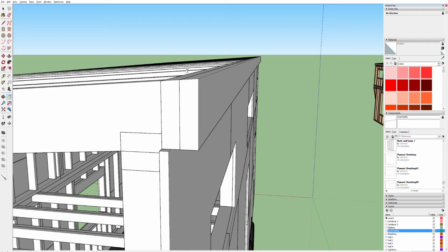And then we're going to have some drip edge, which is basically a piece of steel flashing or any kind of metal flashing that is nailed down to the sheathing and these blocks most likely with an approximately 90-degree bend, and comes down here and then flares out.